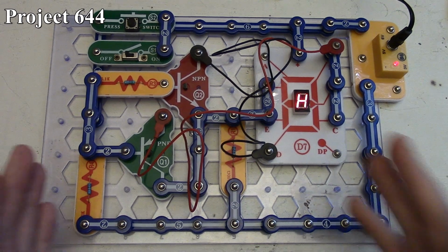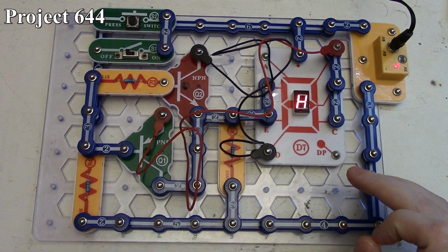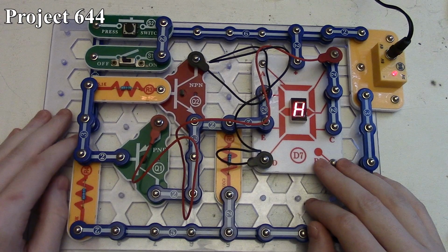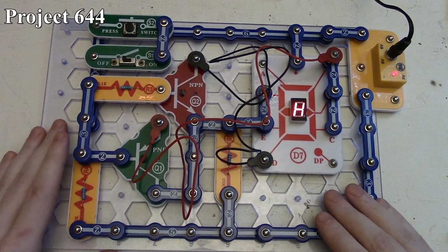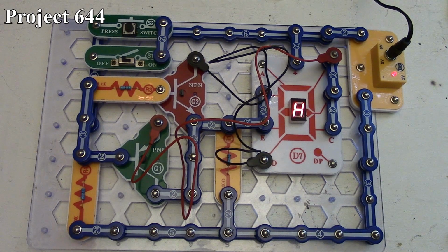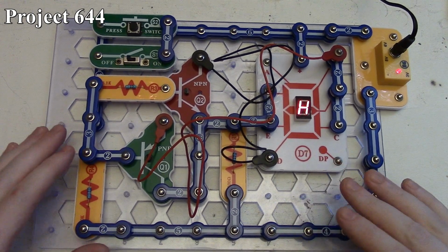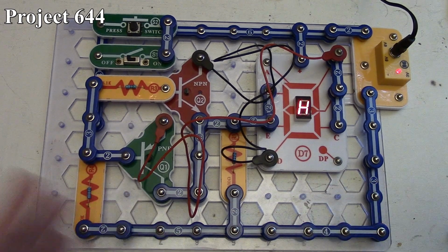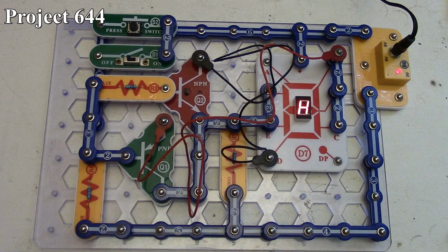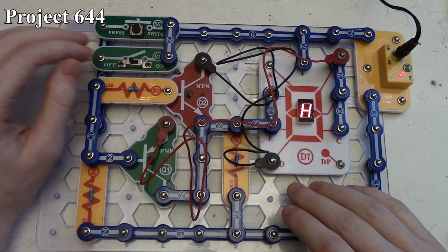So with the OR, if one or both of these conditions with these switches here were true, then we'd have a true output. But now you see when both of them are in the false condition, we have a high or true condition on our 7-segment LED here, because NOR, just like the NAND, is an opposite of the original operator. So we have the OR, but now we're negating the output, so it's always going to be opposite of what the normal OR logic gate or operator works on.